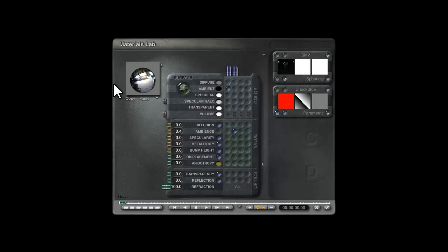Now we've brought the brightness of these lights up, possibly well beyond the ordinary range of ambient output, so we're going to get some stretching of the colours at the other end, because there's not enough information in a low dynamic range image to display high dynamic range, so you will have big steps. So that's what we're expecting to look for. But under this circumstance, we'll just give this a render. Let's have a look where we are with the reflections.